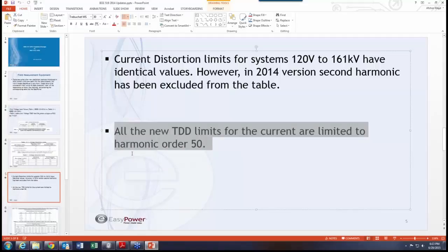I'm sure for communication engineers it might be in the lower bands, but for us as power engineers it's really high. You don't see a whole lot of them, but now it has become a requirement. So what it says is forget about any harmonic higher than 50th order. Don't even consider it. We don't call it a harmonic order anymore. So that's what it says.